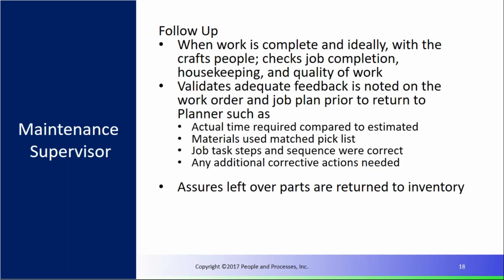And then when the technician finishes up, did we do what we said we were going to do? Was it done the right way? Was the quality right? Did we get the feedback right? Coming back to the planner, or in the case of emergency or urgent work, the planner typically doesn't see that. So did we make sure we've got it documented well there too? And actual time versus estimated.